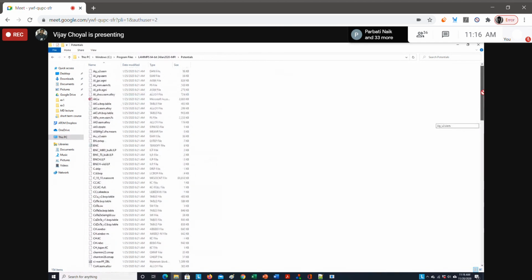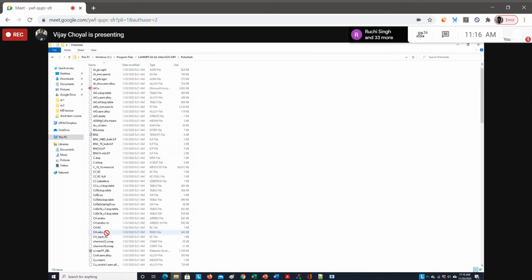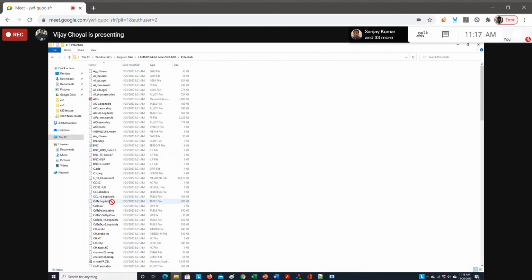If we are using boron nitride nanotubes, our nanotube having boron and nitrogen, so we need such a potential file with the coefficients related to boron and nitrogen. So this is a potential file we can use. But also if your system is having carbon nanotubes, then you can use the REBO and AIREBO potential also. AIREBO is also available here.